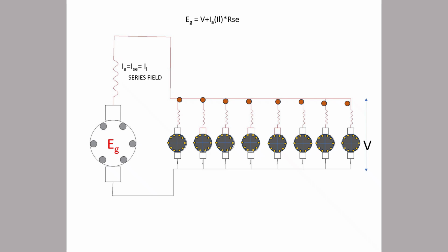as AC form, and then it is rectified by a circuit into DC, but it is a pulsating DC. We need smooth DC, so we use a filter circuit like a smoothing reactor and capacitor. If there is any change in the inductor, a voltage will be induced in the inductor and it will oppose the very cause of its induction.